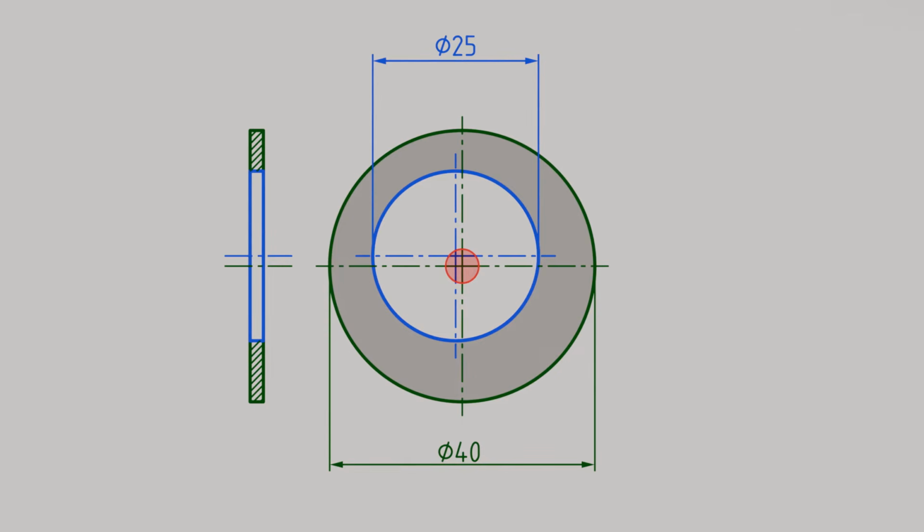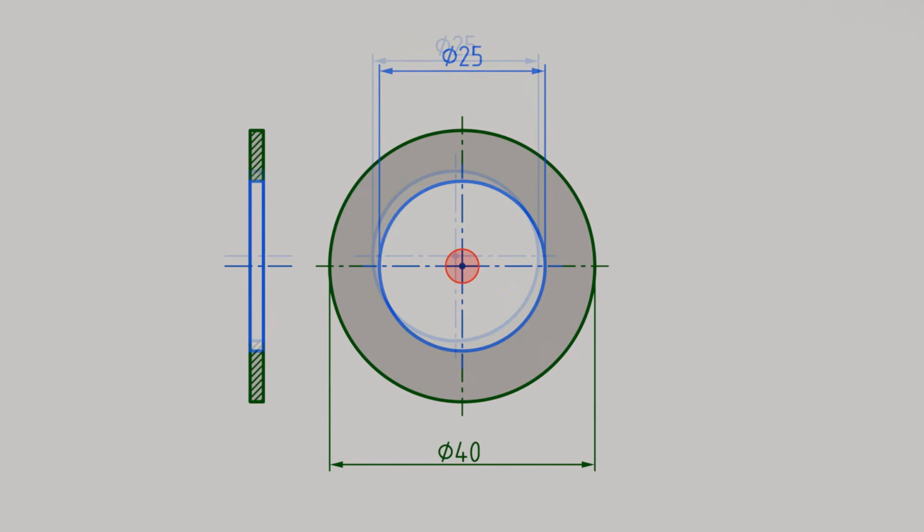In principle, it is extremely difficult to determine the centerlines of such thin metal sheets using measurement techniques, as they are extremely short and therefore practically non-existent. In such cases, it is not the centerlines but the center points that are toleranced. In this context, we no longer refer to coaxiality, which applies to the centerlines of cylinders, but to concentricity, which refers to the center points of circles. However, the principle for establishing the tolerance zone remains the same.